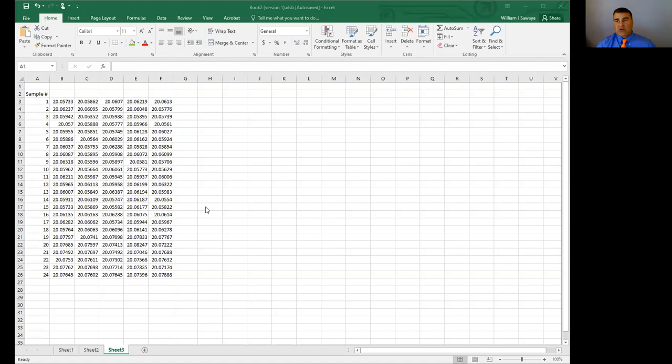All right, so now I'm going to share an Excel spreadsheet that I've made. So here's what we would do. We would say, let's measure, say, 5 of these parts a couple of times a day. If you're putting together a sampling plan to build a control chart, you want to minimize the variability within the sample and maximize it between samples. So if I want the minimum variability in a sample, I'm just going to pull 5 parts in a row as they come off the assembly line. I measure that particular dimension, and I have 5 measurements, right?